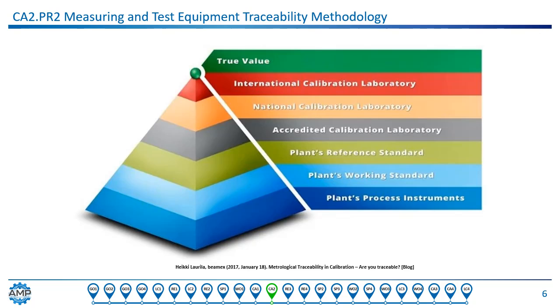Every MTE we use to calibrate or test our process instrumentation must be linked to a tangible accepted standard and pedigreed with documentation attesting to that. The term measurement traceability is used to refer to an unbroken chain of comparisons relating an instrument's measurements to a known standard. Calibration to a traceable standard can be used to determine an instrument's bias, precision, and accuracy. It may also be used to show a chain of custody, from current interpretation of evidence to the actual evidence in a legal context or history of handling of any information.